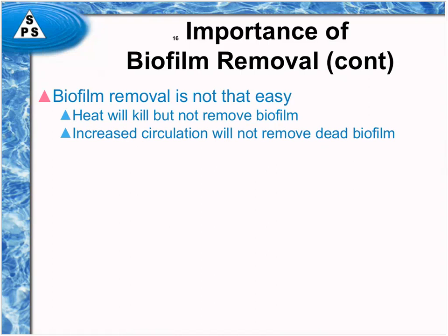Even if you increase the circulation to, let's say, very, very rapid circulation during this process, it will not remove all the dead biofilm. The shear forces of that circulation are not what you think they are, and so it doesn't actually get down to the actual base surface of the pipe to remove a lot of the biofilm that's growing in that fairly slow-moving boundary layer that's right next to the surface of the pipe.